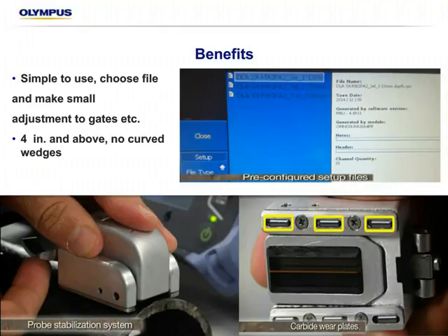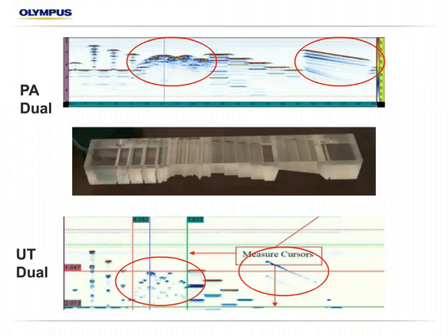So here's a few acoustic performance examples. This is a Rexolite block, or lucite, plastic anyway. But it's a very good representation because it has all the types of targets we typically want to be able to detect when we're measuring corrosion. Here we have some flat milled steps. We have some simulated corrosion that was actually laser etched based on looking at actual corrosion profiles. We have the normal step wedge that a lot of us doing thickness readings would be familiar with. We have a slope of varying angle, and then we have a small notch in there as well.